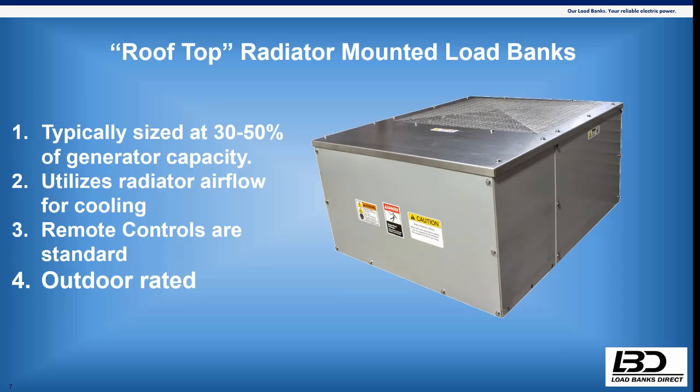We have had instances, maybe not a rooftop, but like a 500 kW genset with a 250 kW load bank, and they put it into the custom Pritchard Brown walk-in enclosure. It's all installed, it's 480 volt, and they say, no, it's not, it's 208 volt. Well, just reconfigure the load bank for 208. No, you take the whole thing out and put in a new one. It's a major amount of rework. So it's really about getting the right information, and we're pretty good about that. The LBD is very good about that. If we feel we don't have the right information to start, we'll come back to you and make sure that we ask for it.